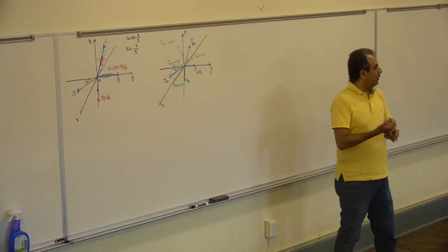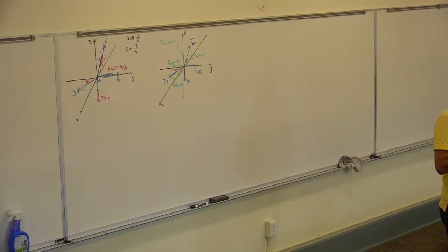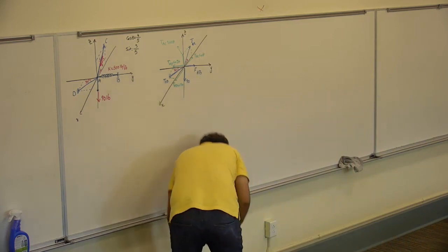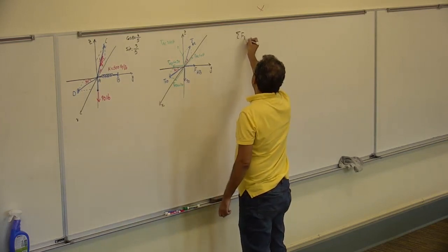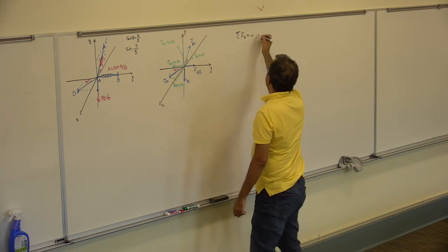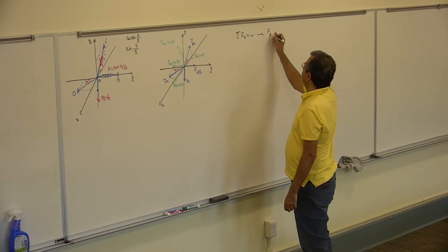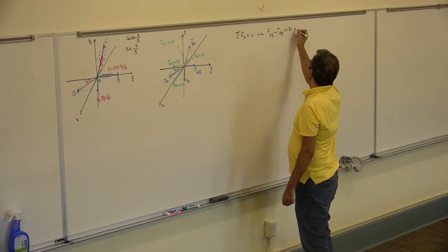So now I have all the forces in the x, y, and z directions. Right? So what should I do? Just sigma Fx = 0, sigma Fy = 0, sigma Fz = 0, if I want equilibrium. I'll write sigma Fx = 0. If I write sigma Fx = 0, it will give me FAB minus TAD cosine 30 equals 0.